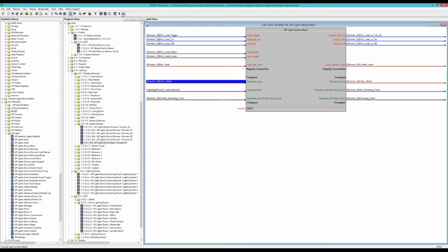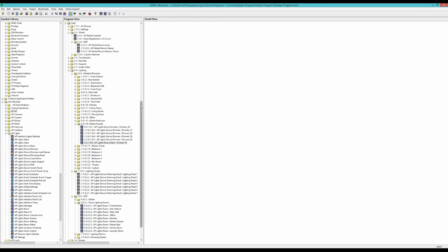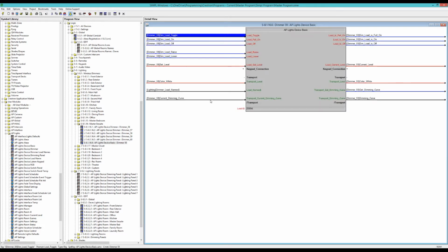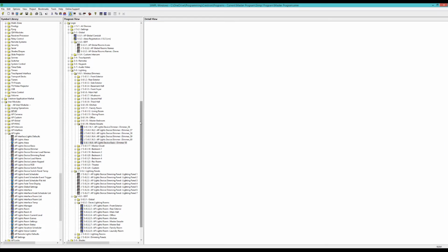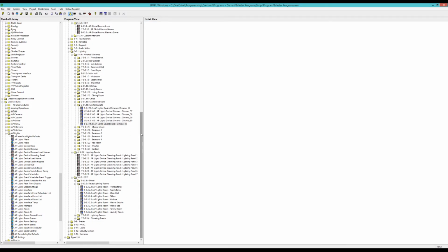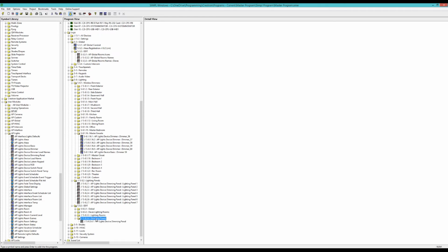If you don't really care about the RGB color changing. And also, most RGB strips that I've dealt with are just RGB. There's no W, whereas the controller has the white control as well. So you can use this single load driver to take over the white output of that same module and control an RGB load and a single light load all from one controller. And these modules can be considered 100% independent of one another. So that's the lighting rooms there.